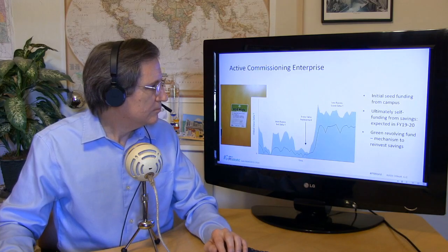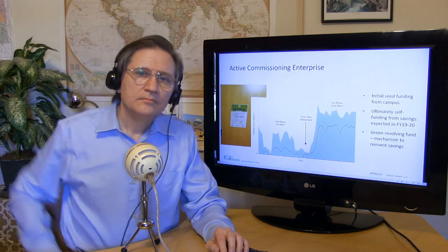And then that feeds into operational collaboration, because all of a sudden there's enough information for folks to actually substantively collaborate. Whereas before, it could just be like, hey, our chillers aren't running efficiently, what are you guys doing? And they might say, we have no idea, or we have to drill in and look at the different buildings. But now it's all there in a single view. And similarly, a building operator could look at a building and see a building that's high flow, low delta T, which is an energy problem, and then either fix the operations or identify a retrofit that needs to be done, or whatever it is.